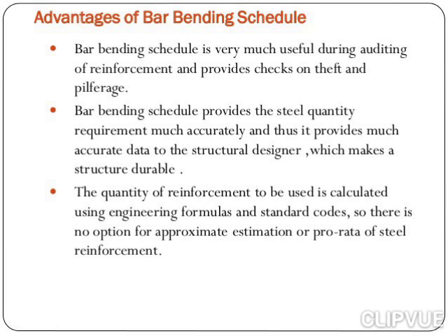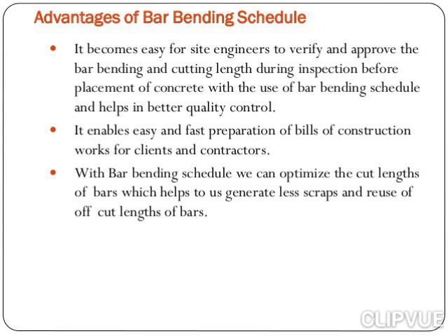The quantity of reinforcement to be used is calculated using engineering formulas and standard codes. So there is no option for approximate estimation or pro data of steel reinforcement. It becomes easy for the site engineers to verify and approve the bar bending and cutting length during inspection before placement of concrete with the use of bar bending schedule, and helps in better quality control.